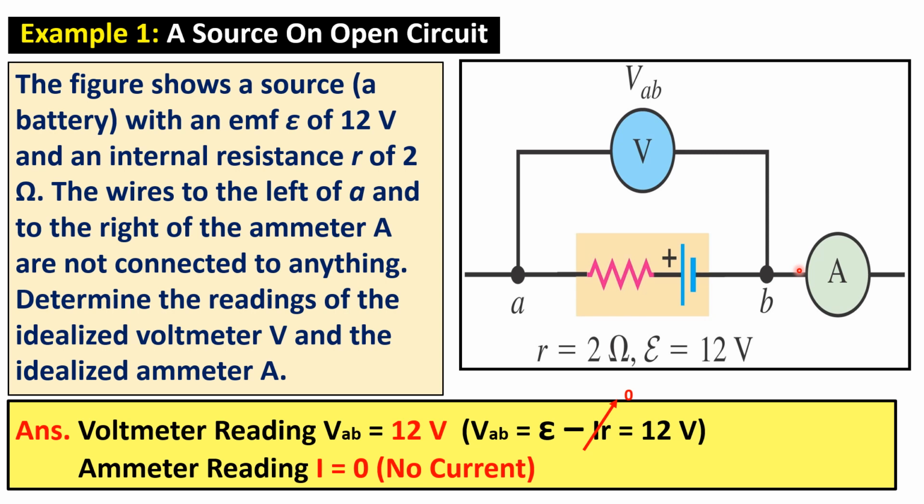So the proper way of using the voltmeter and the ammeter is such that the voltmeter should always be connected in parallel, or across, any device or resistor whose voltage you want to measure. Whereas the ammeter is connected in series with the point in the circuit where you are measuring the current.